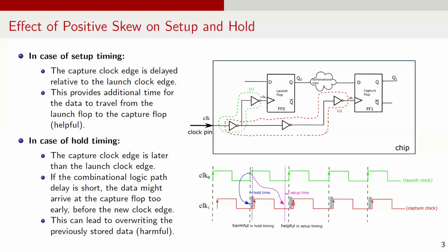This helps the data to meet the setup time requirement and get correctly latched at the capture flop. Positive skew is beneficial for setup timing. However, it can be problematic for the hold timing.